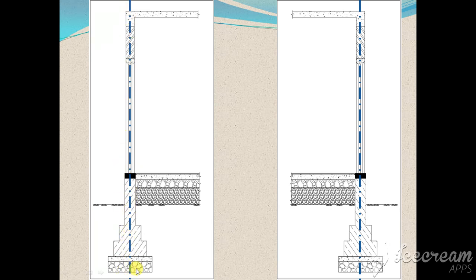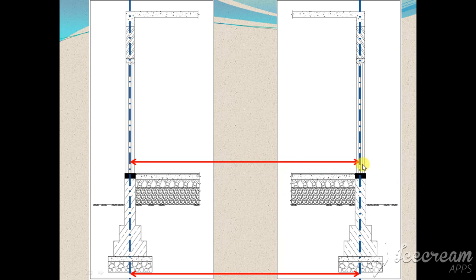This means we can say that the soling, excavation, PCC, stone masonry for foundation, DPC, brick masonry for superstructure, and these beams, all these items can be calculated by using both methods, wherein we are supposed to calculate the center to center dimensions of these center lines, and thereon, by taking the widths and heights, we can calculate the quantity of the particular item of work.